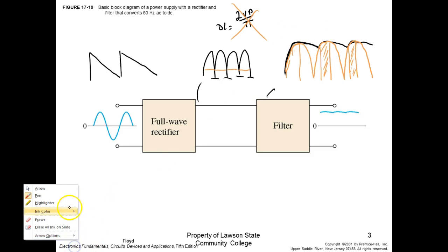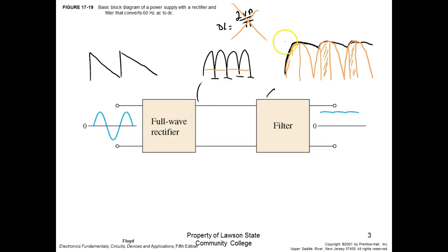So what we look at is we come over here and we look at this guy right here. Let me draw. So what sets our voltage now is these peaks right here. So that would be V peak out, right? It charges up to what we call V peak out. And then it discharges depending on what?